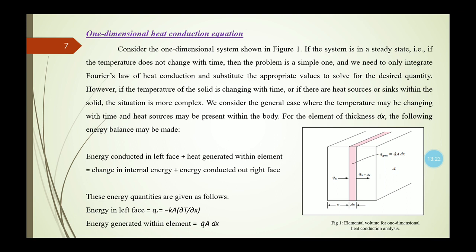So the heat generated within this element also we have considered. This will be equal to the change in internal energy, that is, the change in internal energy inside this elemental volume, plus the energy conducted out from the right face of this elemental volume, which is Qx plus dx. Now if this is our energy balance equation, we need to find the equation for these four different things.